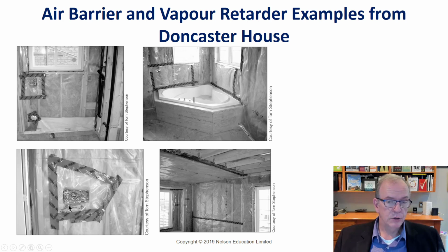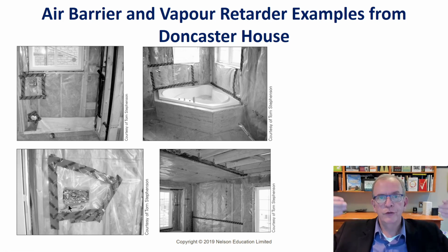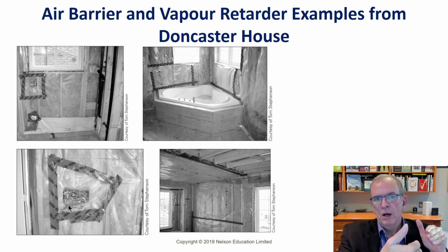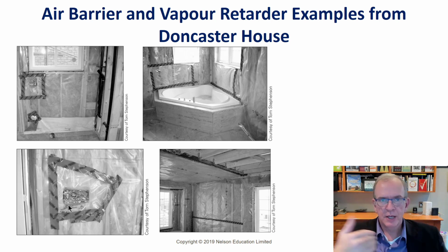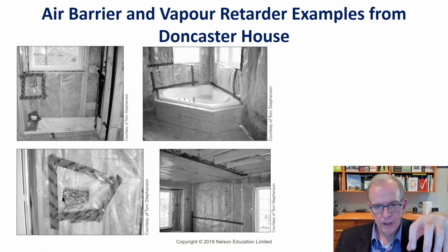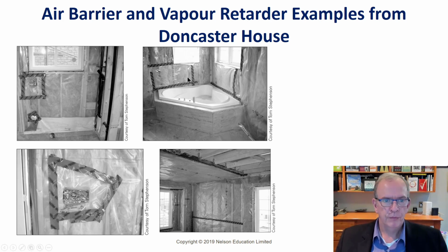In many cases, if you're going for a net zero design, your best bet is to design it so that you have as few boxes and protrusions on outside walls. So don't put a switch box on an outside wall, put it on an inside wall if there's an intersecting inside wall nearby. I've even seen some net zero designs where the outlets are in the floor, with special caps so that you can plug into the floor. That way you don't penetrate the envelope.